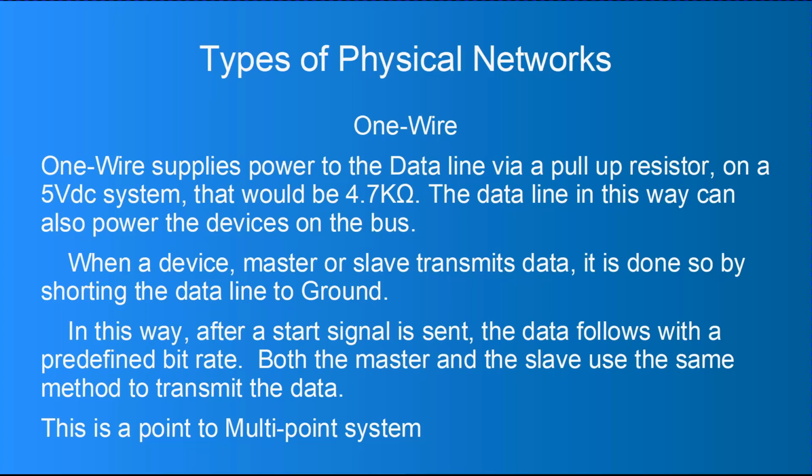So the way these usually work is the master, our Arduino, will send the command to do a conversion. Usually it will send the command to the bus as a broadcast, so it can talk to multiple devices at once, telling multiple devices hanging off the bus to start their conversion, and then it'll drive the bus to a fairly high power level.